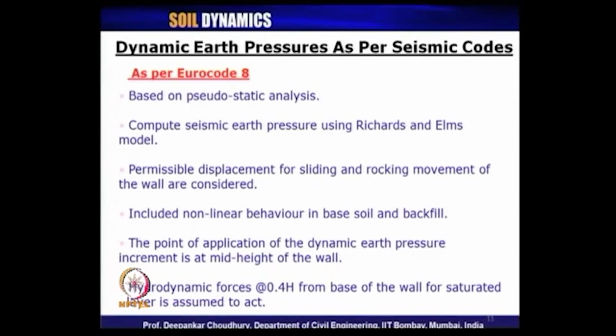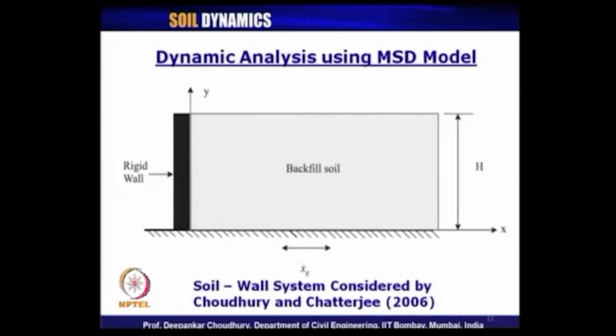And one extra important thing I forgot to mention, in Eurocode 8, they mentioned to calculate the soil amplification also, which is absent in the Indian standard code. So, soil amplification during the earthquake process, the amplification factor, can be considered in our pseudodynamic analysis, whereas in pseudostatic analysis there is no scope for considering the amplification as such.